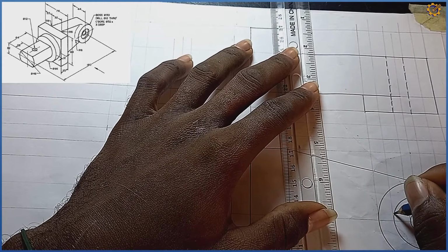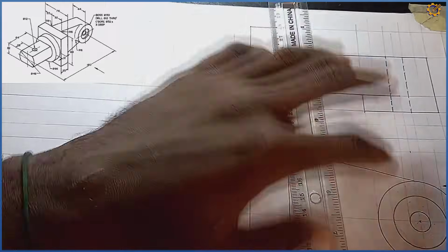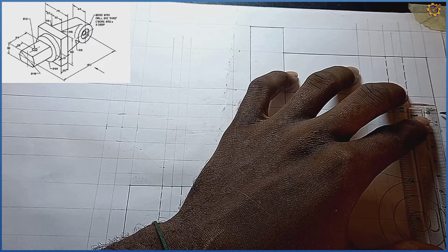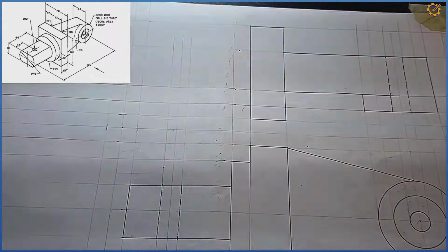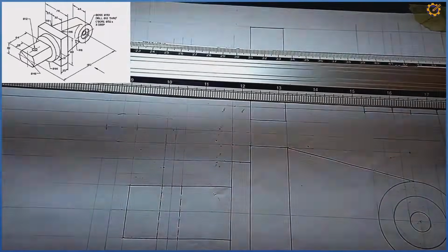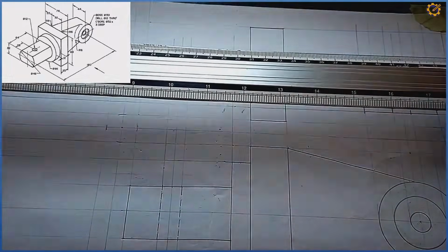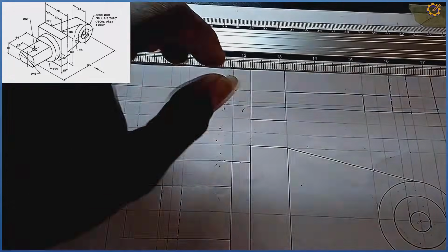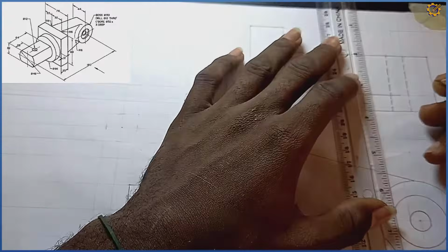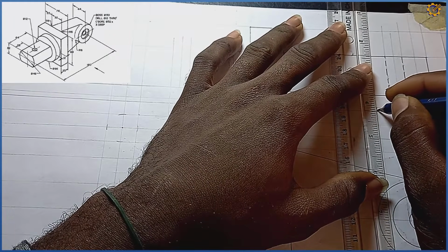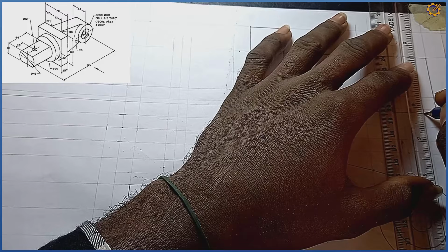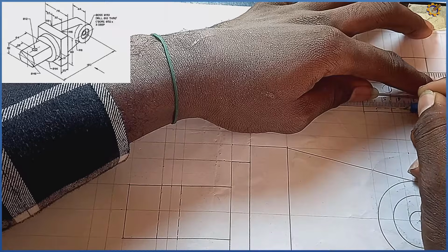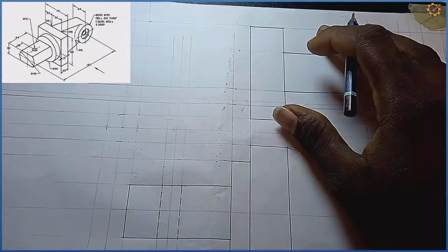Okay. So why this one? We are told that the depth is what? 3. So picking my ruler, standing right at this junction, I'm going to measure a mark of 3, which is this. That mark of 3, I will project it horizontally. Horizontally like this. See? I project it horizontally. Okay, and the next thing I'm going to do is pick my ruler and draw this faintly hidden line here. Also here a hidden line, and this direction is going to be hidden like this. Okay, this area on our plan is settled.